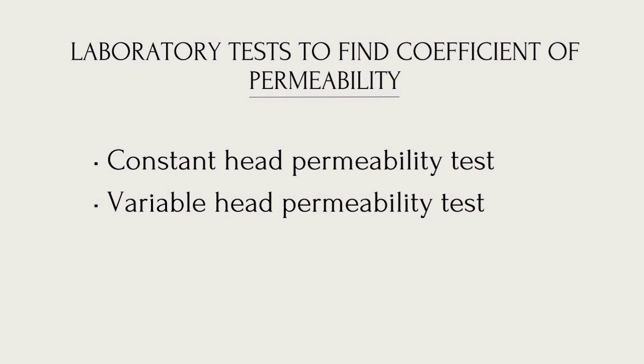This testing method can be applied to an undisturbed sample. This involves flow of water through a relatively short soil sample connected to a standpipe, which provides the water head and also allows measuring the volume of water passing through the sample. The diameter of the standpipe depends on the permeability of the tested soil.